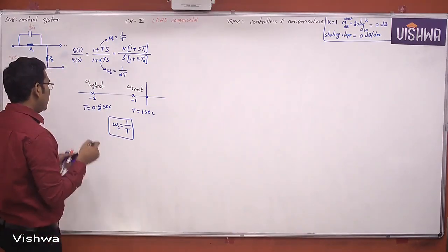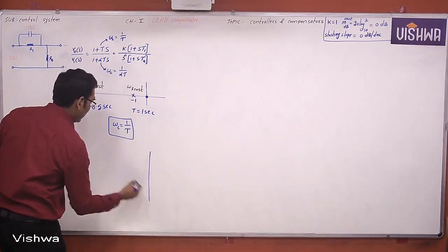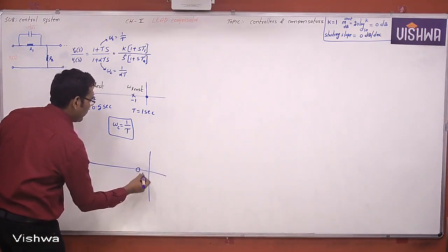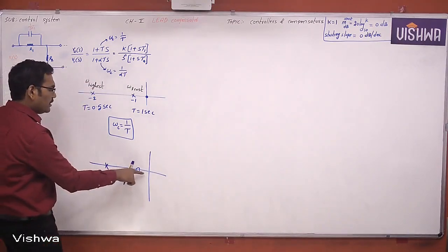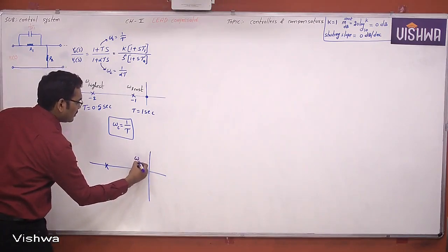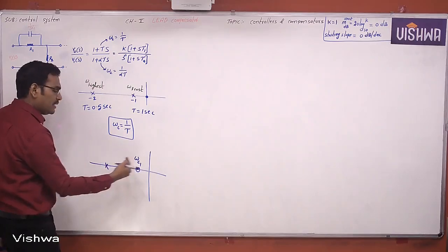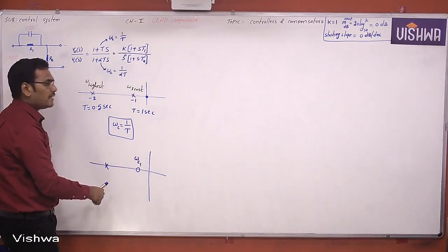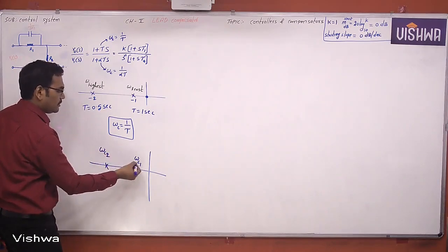So who is nearer and who is away in our compensator? Because just now we finished the pole-zero sequence of the lead compensator. This is the zero, this is the pole. Is it right or not? So the zero is nearer, therefore this is the least corner frequency because this is the highest time constant. The pole is far away, so this is the least time constant and the highest corner frequency.